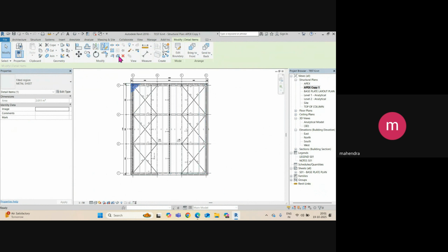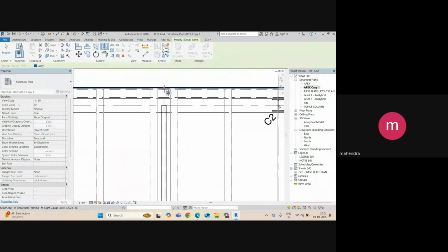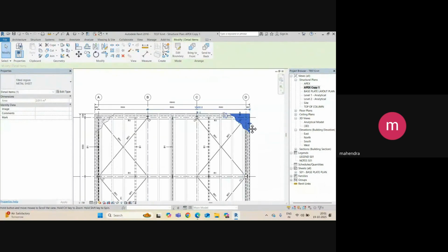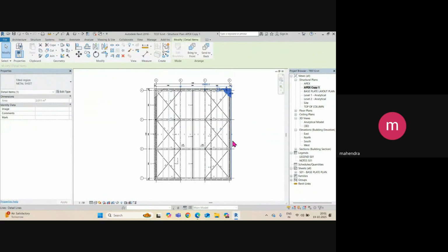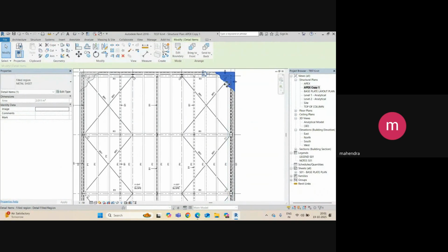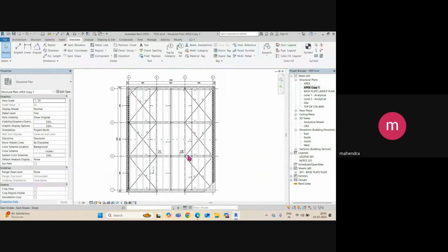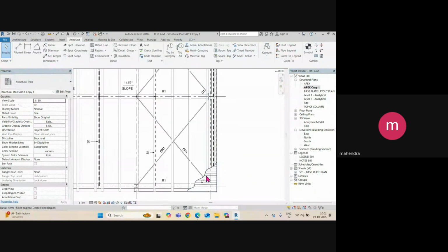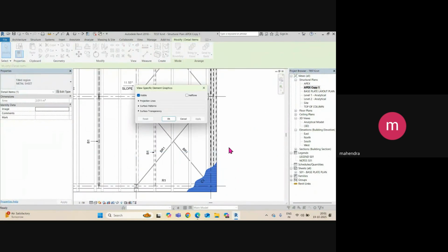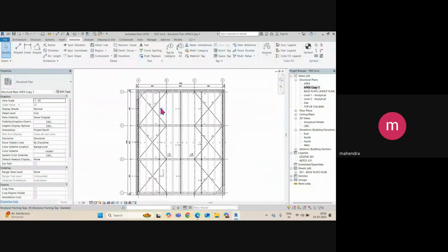Then you can mirror this in this direction also. What I do, I will mirror this exactly, using the center point. Yes, here, so it comes here. Then I want to mirror again in this direction. Type mirror and you can give it here. Then you need to represent it only at the diagonal, here and here. That means all the presentation for the metal sheet. Again you need to set the transparency to 60%. Say apply and okay. You can see this is your metal sheet.